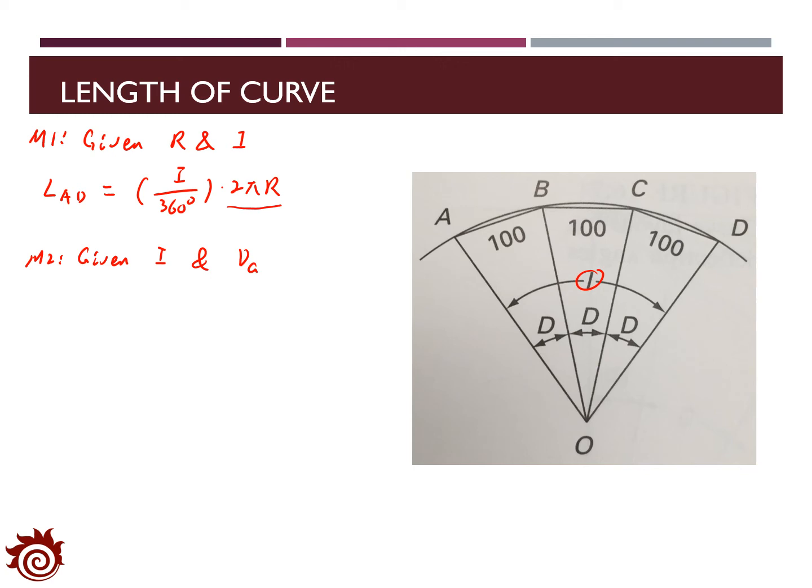Then the length of the curve LAD can be calculated as 100 times I over dA, as dA is defined based on the standard length of 100 meters.